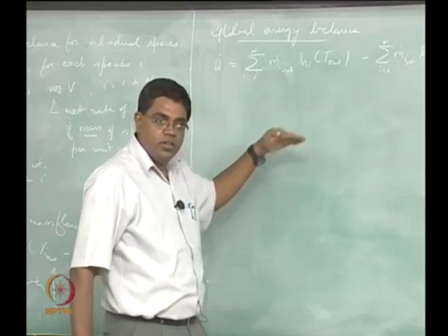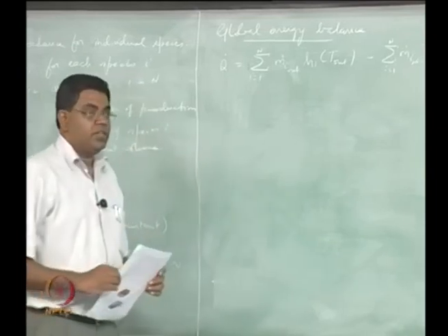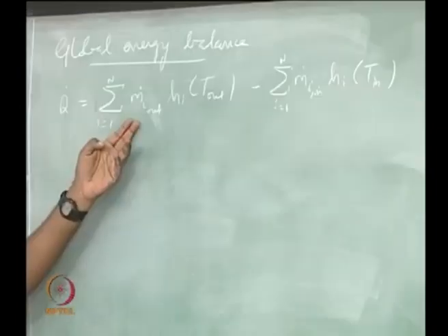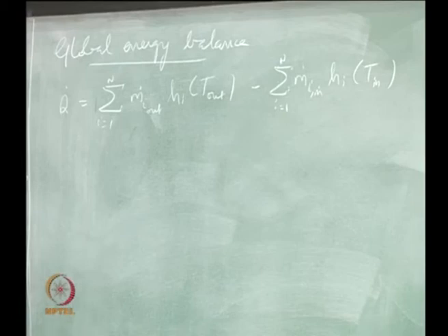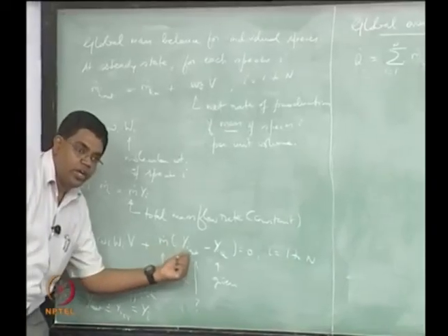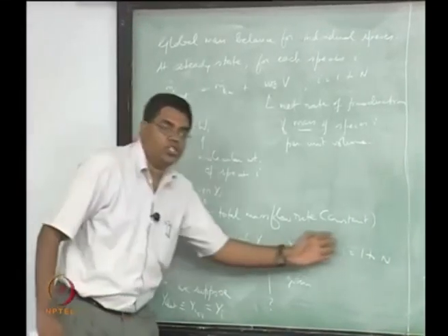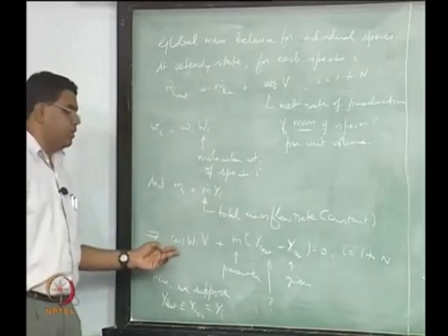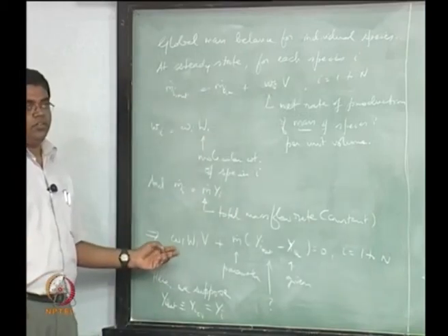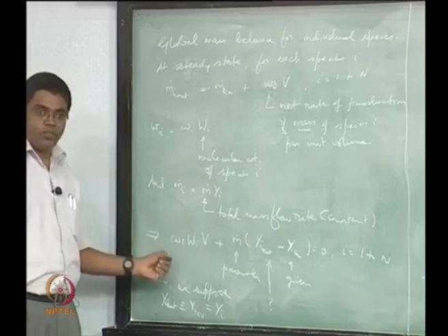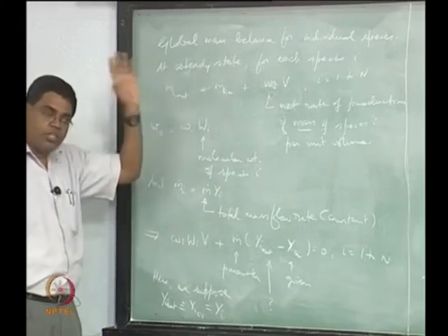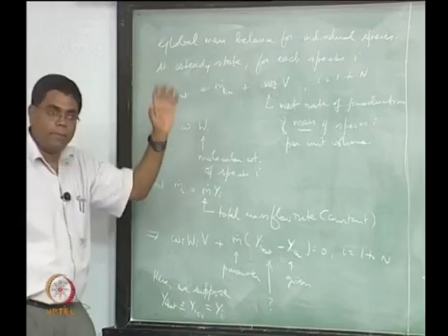You see, except the m dot I out was calculated based on equilibrium calculations earlier on, whereas here m dot I out is nothing but m dot times yi out, and yi is going to be calculated with this equation, taking into account the chemical kinetics. So this is a difference. So this is the real process, that was a hypothetical process, you see.